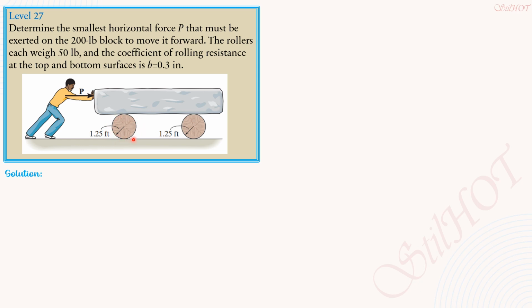a roller, and imagine that there are two rollers already, so that the 200-pound force should be the weight on the upper part. And imagine that there are two rollers, because there are really two rollers. So the principle is we have to locate the point on the ground where the outer surface of the wheel or roller and the ground intersect, or meet, so that's the point where the reaction on the ground and the surface meet, and we sum up moments there.